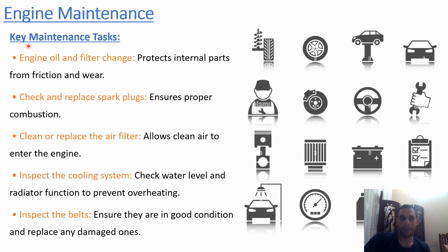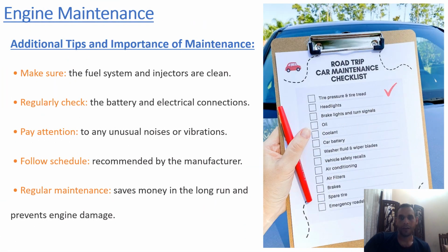Most of the key maintenance tasks, as we can see here: engine oil, check and replace spark plugs, clean or replace the air filter, inspect the cooling system, inspect the belts. This is important to check on our cars and make them run smoothly. Also, engine maintenance should follow a checklist regularly to make sure the injectors are clean, with regular checks of electrical connections. This will help us to avoid any failure of our engine.